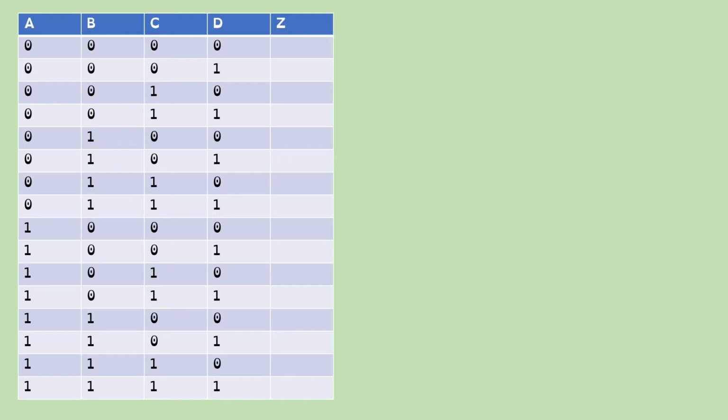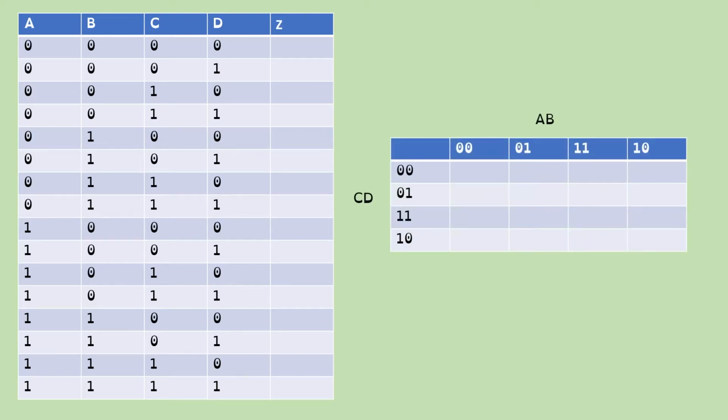We've got 4 inputs, and it's fairly traditional to have A, B, C, D, and for it to be done in binary order, so that you can read the outputs. And we're going to translate from this kind of truth table to the Karnaugh map, which looks like this. Instead of having separate columns for A, B, C, and D, it uses the two sides of the table.